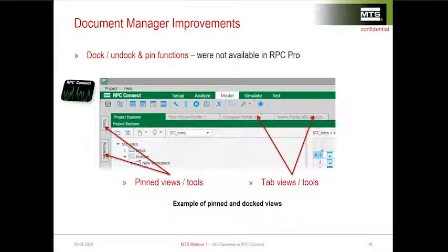Another really nice feature implemented in the software are the dock and undock functions and the pin and tap windows. So we just briefly talked about the tapping of the windows, which you saw when we had the guide diamond, placing the window in the middle. So you can click on these tabs to open any window. Another way of working efficiently with your tools or with your views, so to speak, you can tap them, you can pin them on the left here.